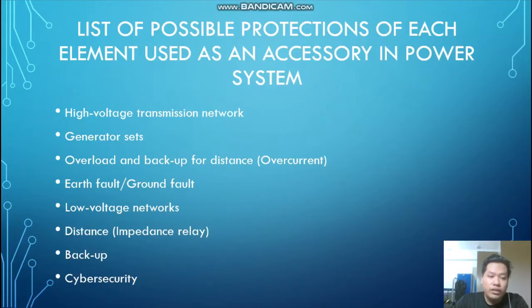Distance protection detects both voltage and current. A fault on a circuit will generally create a sag in the voltage level. If the ratio of voltage to current measured at the relay terminals, which equates to an impedance, lands within a predetermined level, the circuit breaker will operate.